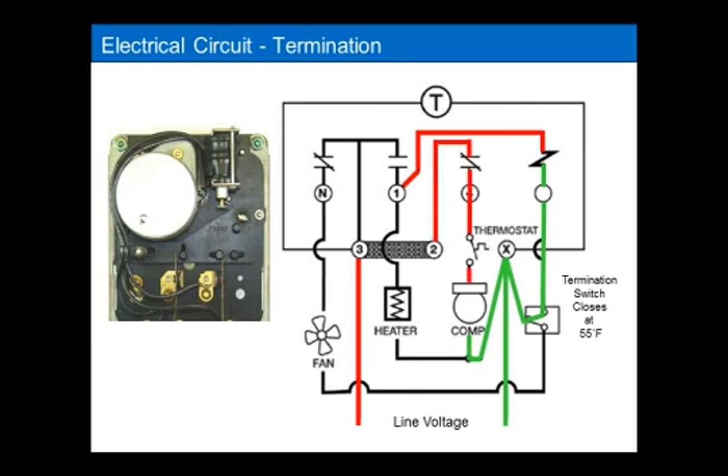Now my compressor's running, but my fans are not, because this switch here, the coil temperature is 55 degrees, so my coil is warm, well not hot, but warm. So I'm not making that circuit back to my fans. Even though this contact here is made, my fans will not be on because this switch here is open.